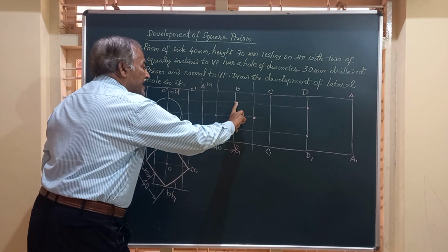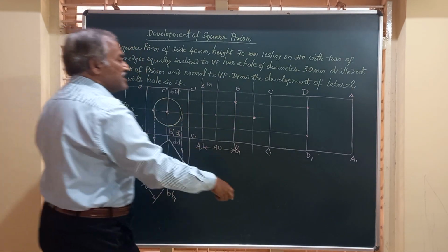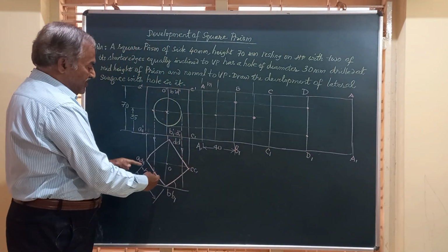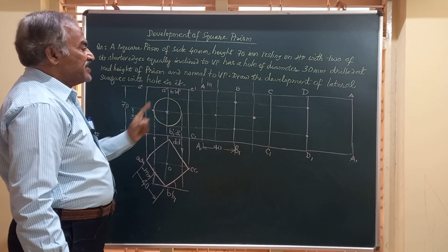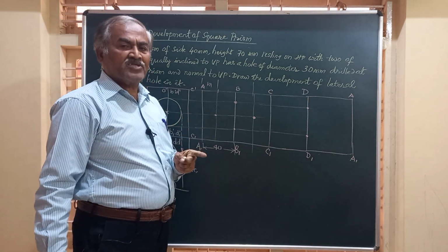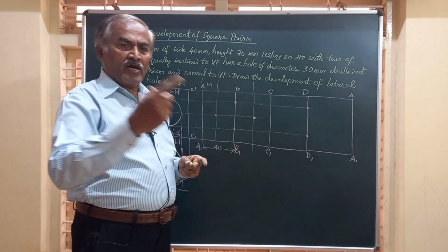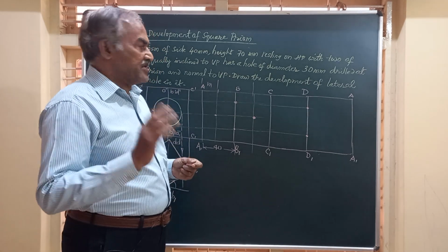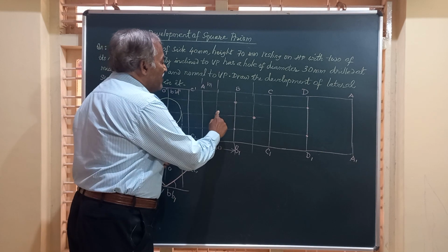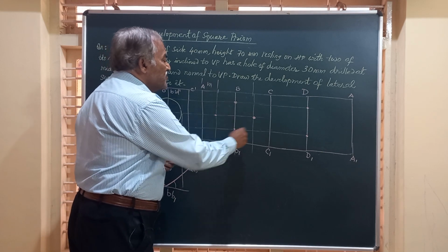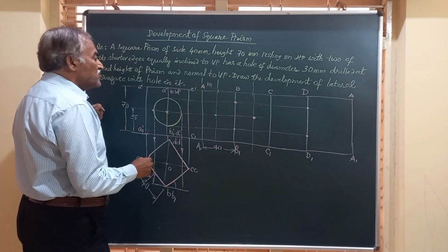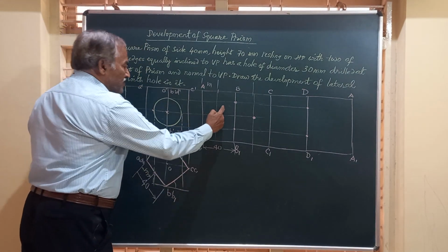The minor axis is equal to the diameter of the circle, and the major axis depends on the diameter, and we have got the value. Friends, we have got 4 points here, so you can draw a smooth continuous curve passing through these 4 points. But what happens if you don't have points in between? The curve you get, the ellipse, may not be very smooth. So I would like to have some more points.